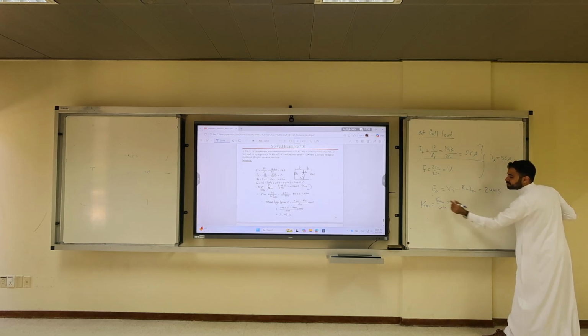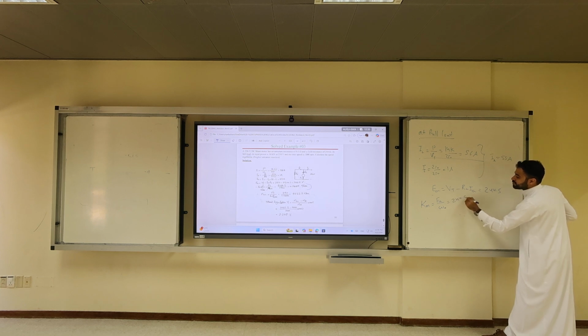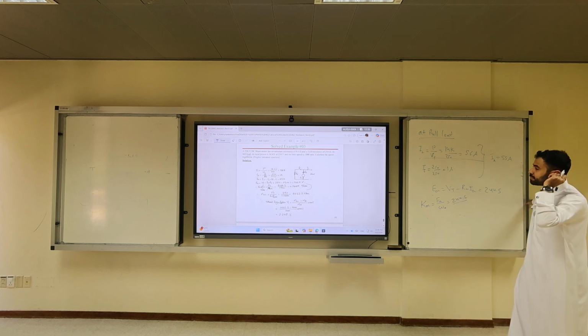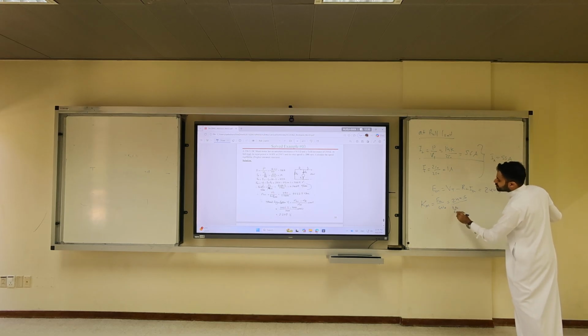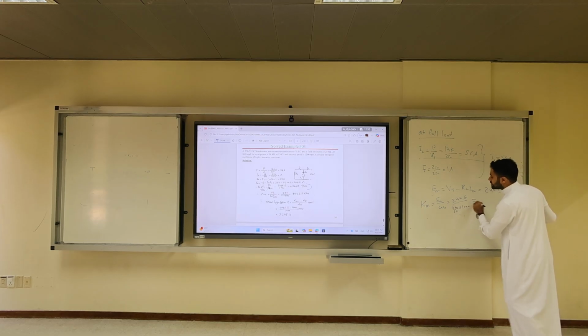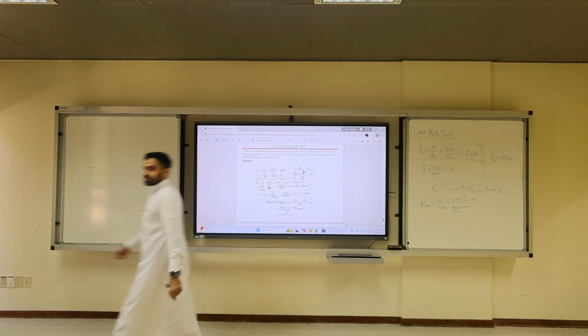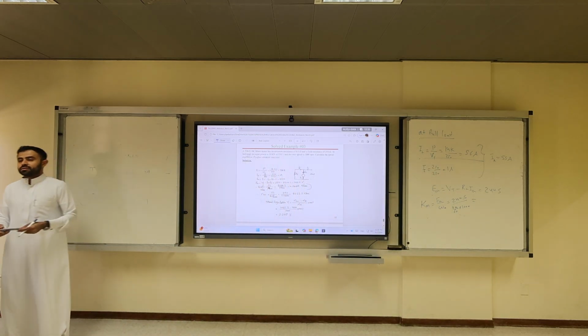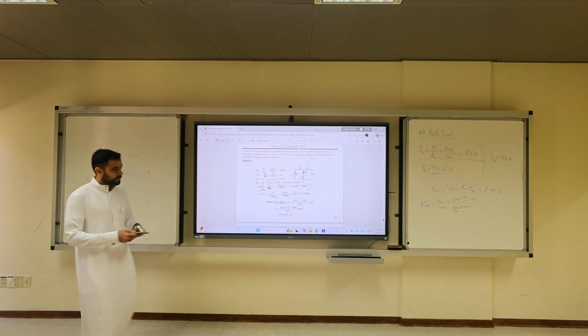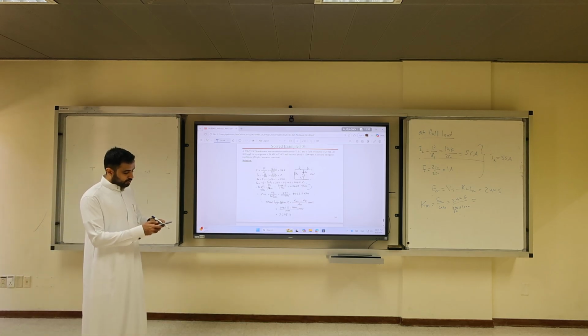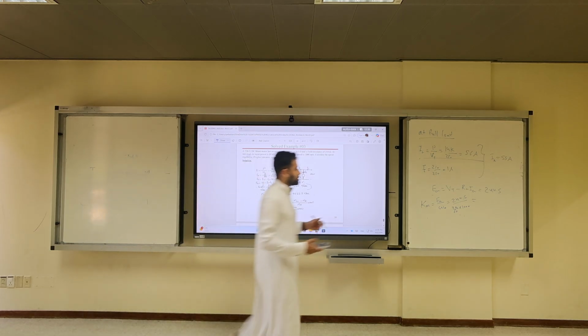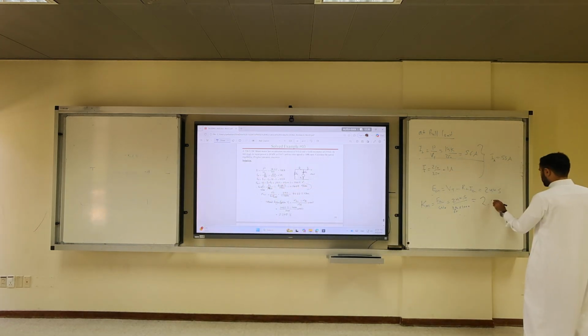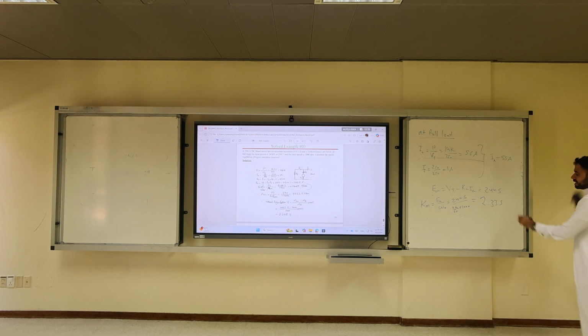What is the constant Km? 244.5 over omega M. What is omega M? 2 pi over 60 times 1,000. I want the answer, please. Calculators. Nawaf, where is your calculator? I forgot. 244.5 over 2 pi times 1,000. 2.335. Okay? What's the unit? Volts over radians per second.